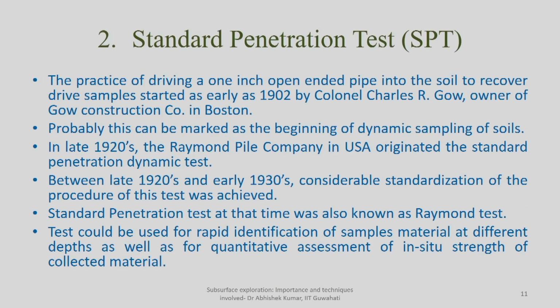Now we will go for another test as we discussed earlier. This test is called the standard penetration test, also known as SPT. Before going into detail about the test setup, how you do the test and interpretation, let us hear about the history of this. The practice of driving a 1 inch diameter open-ended pipe into the soil. So you are actually driving some pipe into the soil so that you will be able to bring some sample from that particular depth onto the surface.